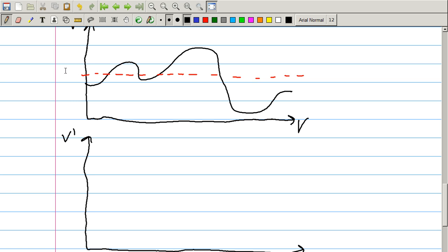So we'll call this Vin plus, and we'll call the waveform Vin minus, just for the sake of a comparator. So right about to here, and this is going to be tedious, but I will do my best. It is below the reference voltage, so it's going to be, I'll use red again, it's going to be low. Then, till about here, it becomes high.